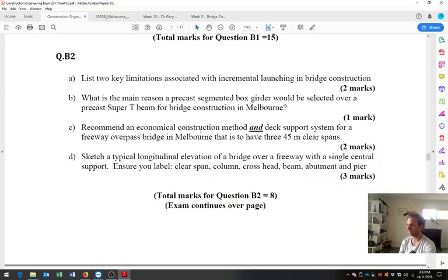So I actually think neither. I think if you're using one of those steel composite box girder bridges, you can just crane in the steel box girder and then cast your slab on top. So it's sort of whole span craneage, I guess would be the answer there.